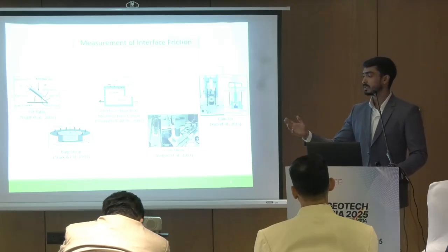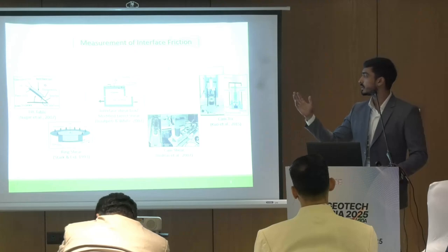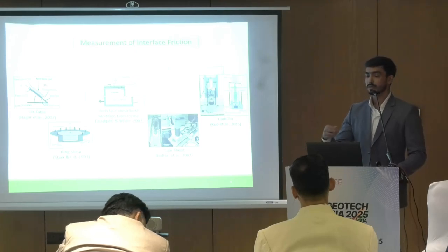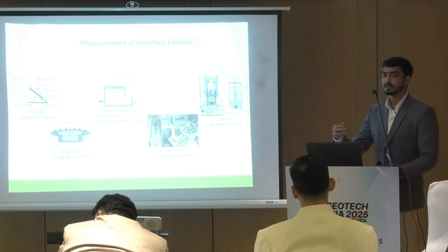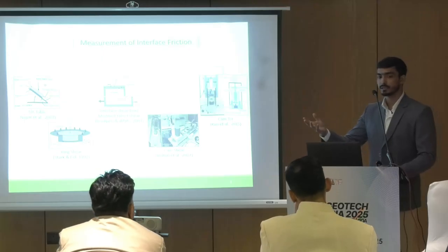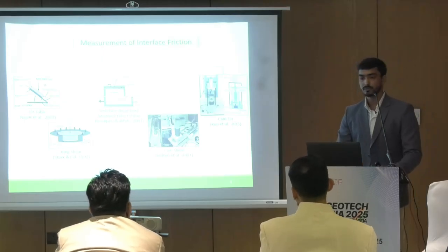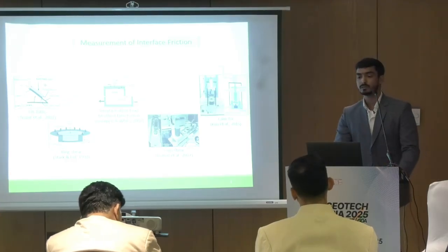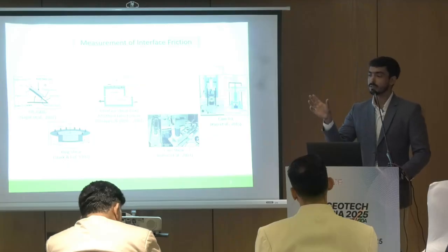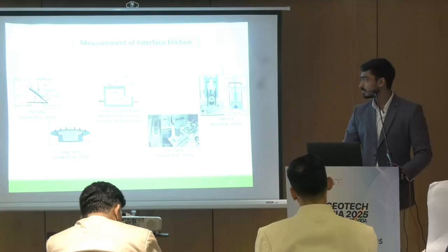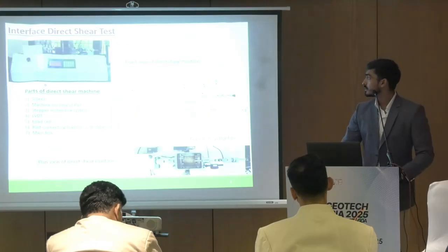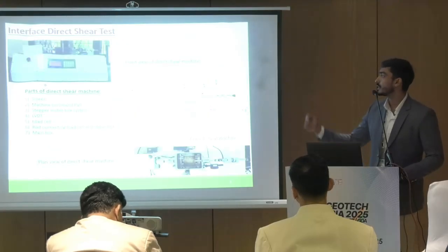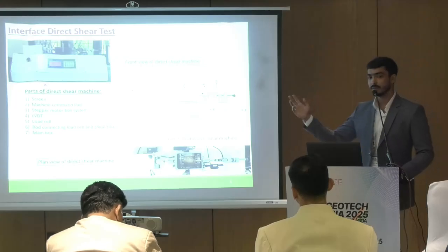So at 10 kPa, most of the direct shear machines work on very high stress. So it was a challenge for us to modify the direct shear machine to operate at low normal stress, because the load cell we mostly use captures high stress. So this is the computer operated direct shear machine which we have used.